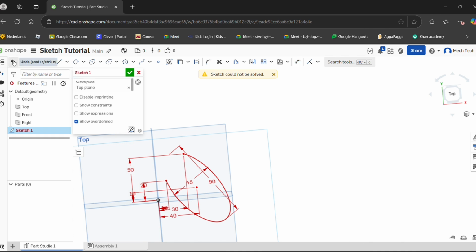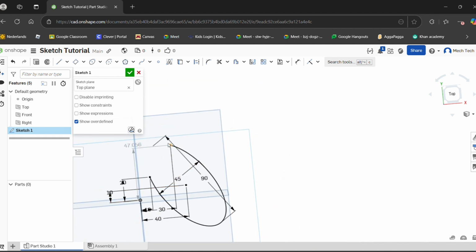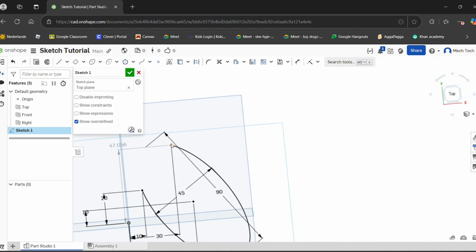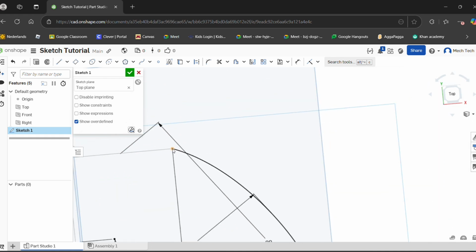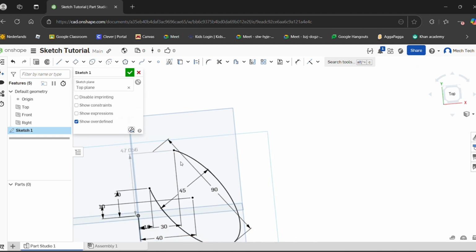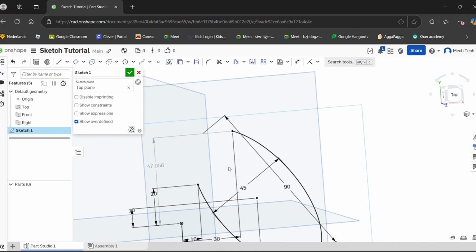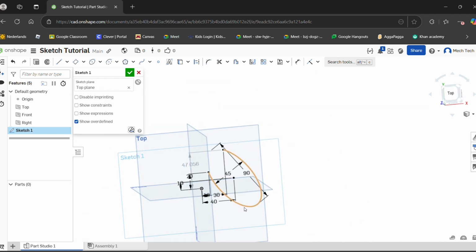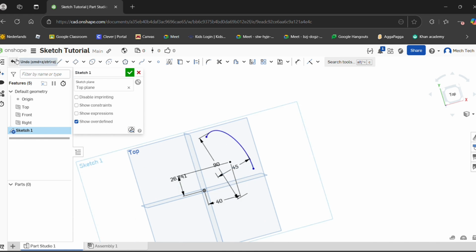Oh, sorry. This actually is fixed because if it is 30 millimeters across, there's only one measurement for that point being 30 millimeters across, because there's no other part of the ellipse that is 30 millimeters across and above here. So this is fixed. Yeah. So now that we have our fixed center point ellipse arc, we will move on to the next one.